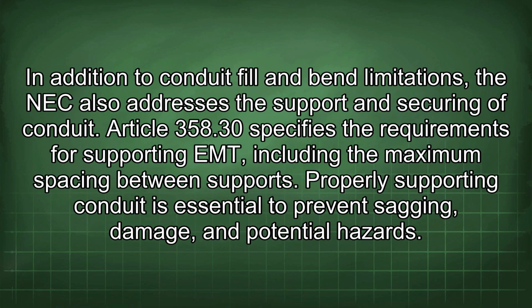In addition to conduit fill and bend limitations, the NEC also addresses the support and securing of conduit. Article 358.30 specifies the requirements for supporting EMT, including the maximum spacing between supports. Properly supporting conduit is essential to prevent sagging, damage, and potential hazards.